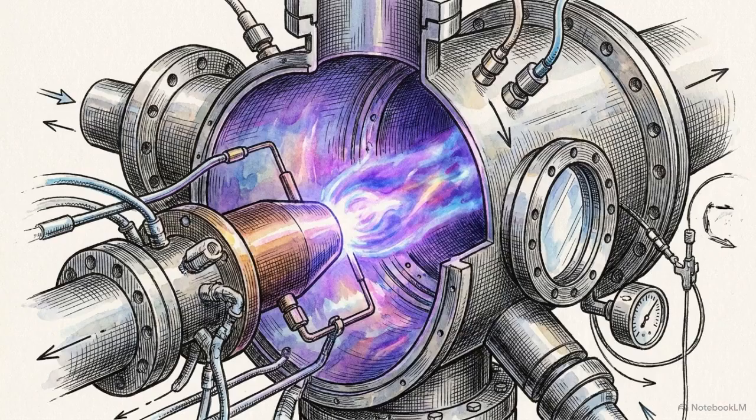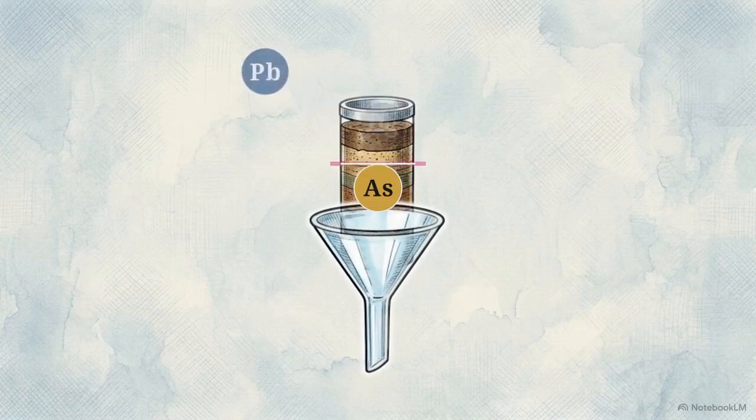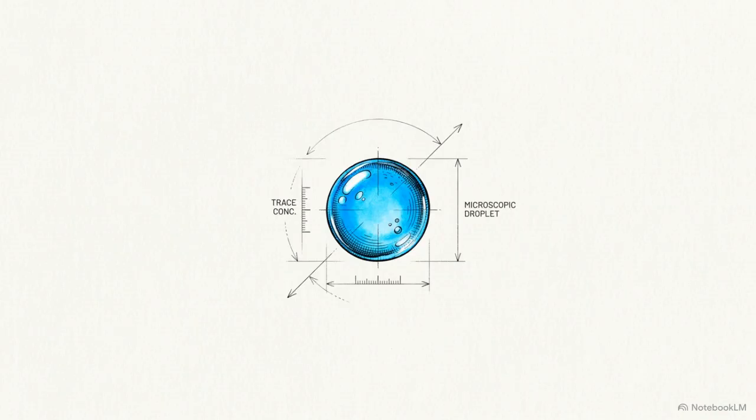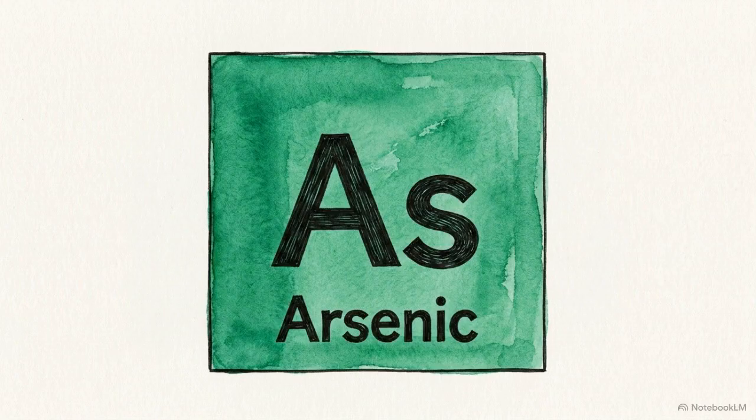For inorganic pollutants, labs rely on a distinct method, inductively coupled plasma mass spectrometry, or ICP-MS. ICP-MS is the industry standard for analyzing marine water and benthic sediments for heavy metal pollution. It operates with enough sensitivity to pinpoint trace concentrations of mercury, lead, cadmium, and arsenic.